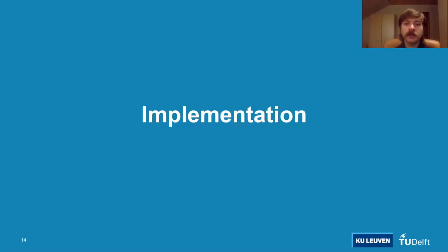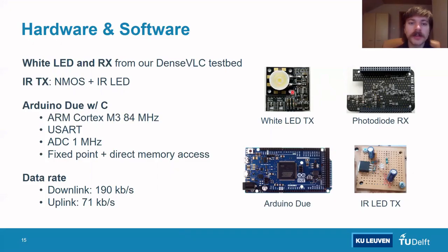Okay, so now I will show you our testbed, which we used to perform our experiments on. We reused the white LED transmitters and photodiode receivers from our previous work, Dense VLC. Additionally, we use a simple infrared LED transmitter made up of an NMOS driver circuit and an infrared LED. Each AP and each user device is equipped with an Arduino Duo microcontroller on which the LightTour protocol stack is